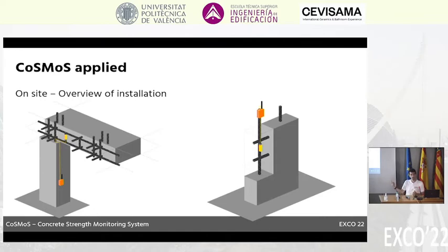The only thing that remains in the concrete is the sensor with the cable that you just cut off, and it's left there forever. Now we're also starting to assess new methods of using those sensors to assess, after the structure is finished, thermal runaways in the building and so on for energy efficiency, because you already have temperature sensors installed all over your building.